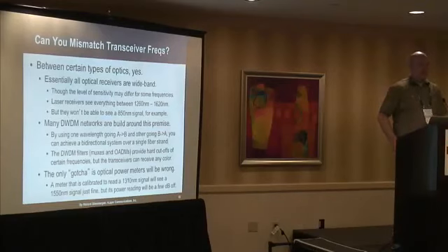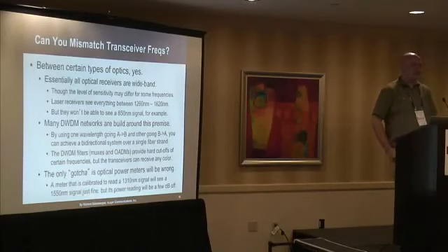Many BiDi systems are actually built around this. You don't need two strands of fiber for transmit and receive. You can put them on two different wavelengths on the same fiber and receive on anything. The only gotcha here is that when you use an optical power meter, it actually has to be calibrated to the wavelength that you're using. So if you've got the power meter set to 1310 and you're expecting a 1310 signal and you get a 1550, it's going to be wrong by a few dB. So you need to know what you're doing to have the power meter work correctly, but otherwise it works perfectly well.